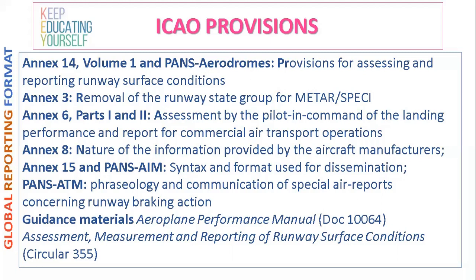What has actually changed is that the pilot requires the runway condition code, he will enter it into his FMS, and if he does not get that value, he will not make an approach below 1000 feet. So this will give him the actual landing distance required for a type of runway surface condition.